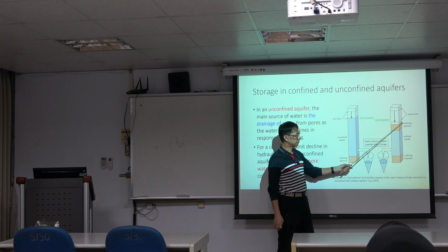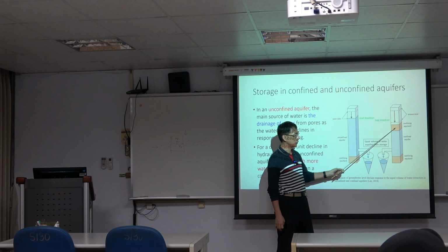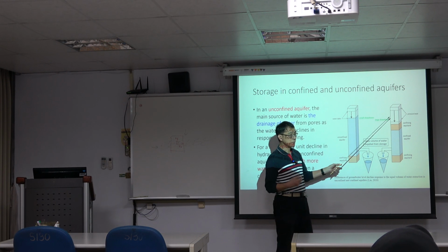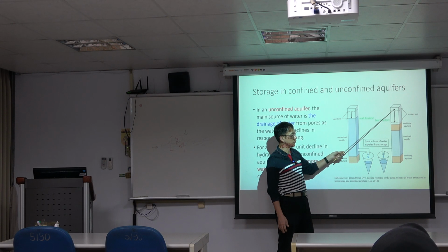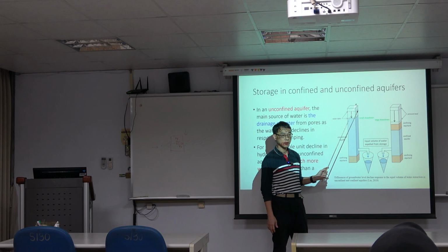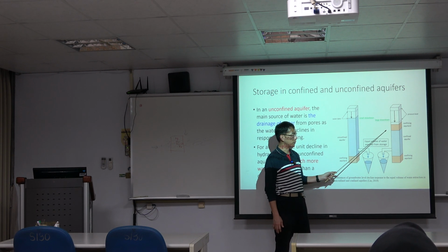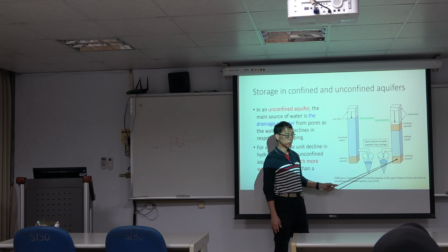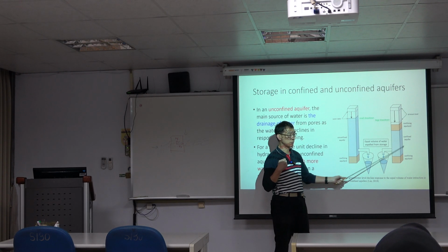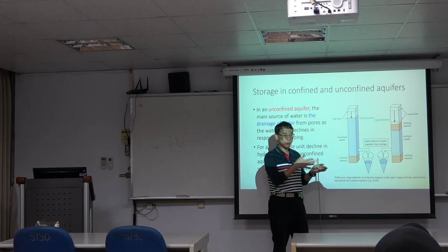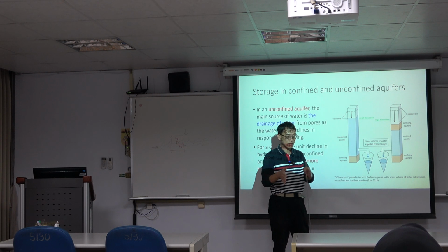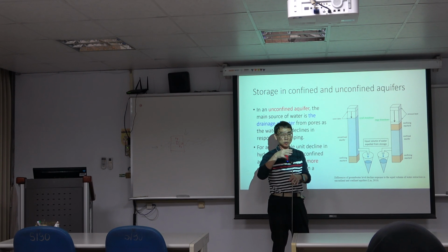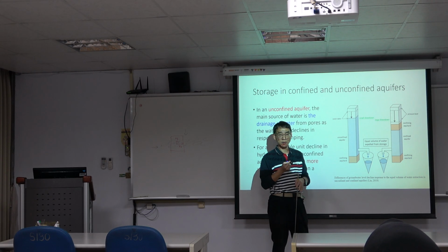This is a confined unit. In this confined unit, the water is fully saturated. And the imagined levels will be here, the pressure levels. And after we take the water, the pressure level declines. Okay? So the question will be, originally these volumes are fully saturated, and you take the water out, but they are still fully saturated in these columns. So before, it's fully saturated at the red column. After, it's fully saturated at the red column. So how can you get the water? Okay, that's the problem.